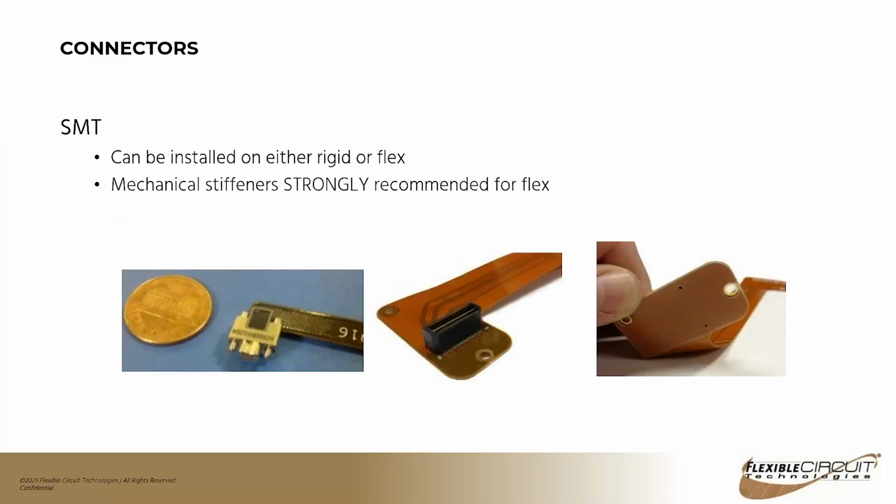Surface mount connectors have definitely become more common when compared to through-hole connectors. Through-hole connectors are often done through either hand soldering or a wave application. Surface mount, with the new equipment that's available today, is very, very fast. The solder paste is screened on or inkjetted on, and then the machine places the connectors, and then it's run through a reflow. So it's a very, very efficient process.